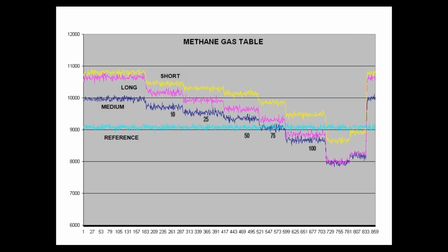Where Delphian can actually say, we can set up 3 different IRs for those 3 different gases, and when you have a leak, we can identify what gas it is, and all 3 IRs can give you a response that's accurate for any one of those 3 gases. And the way we do that is, again, we have 3 channels of detection. There are 3 detectors with 3 different wavelengths.